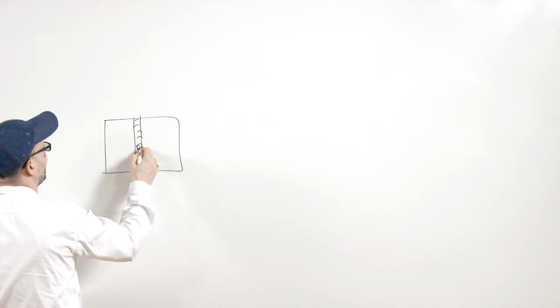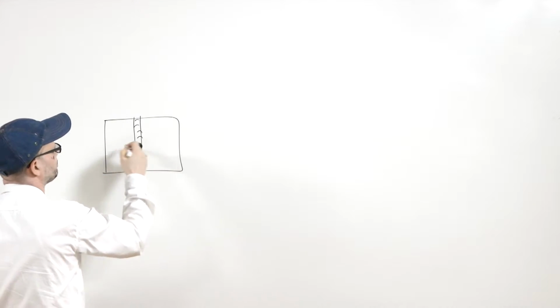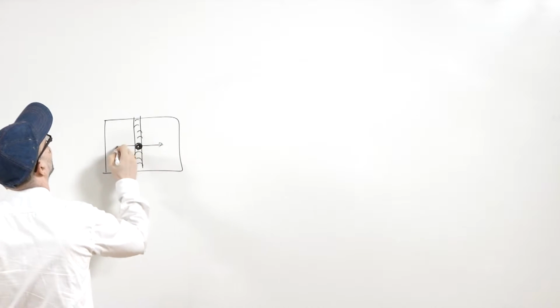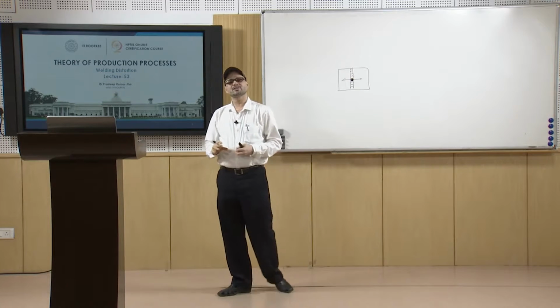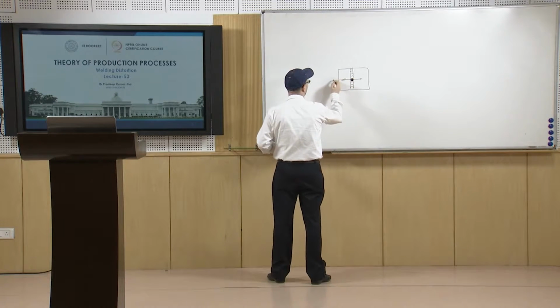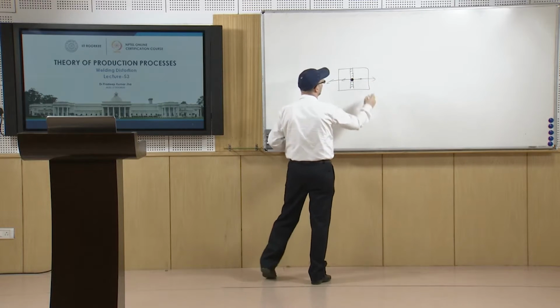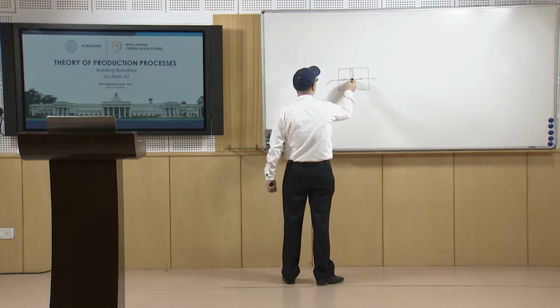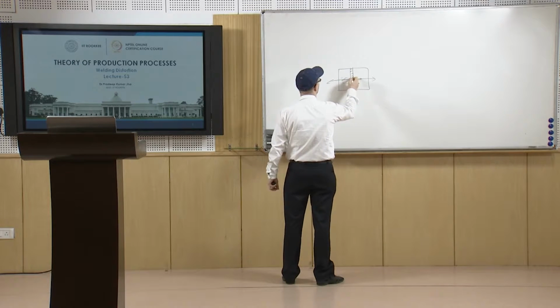welding. So, here once you are heating at this point, now the heat has to be extracted from here and from here. Now, if the thermal conductivity is high, it will quickly pass through it and then go to the surroundings. Otherwise, the heat will be contained for more time in this zone or this zone or even in this zone.